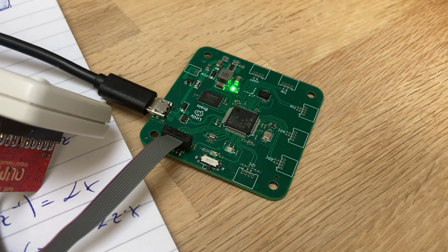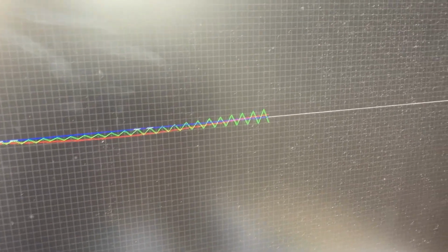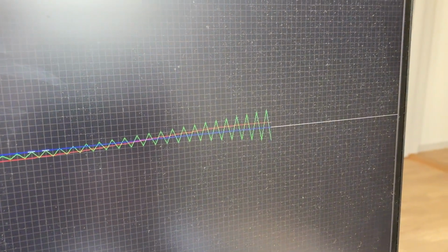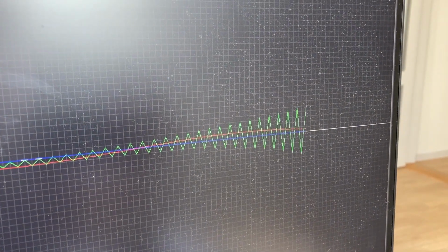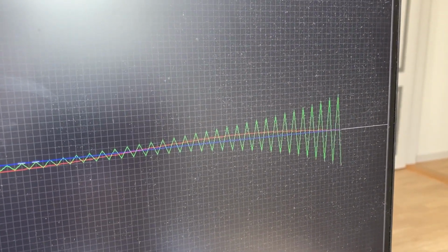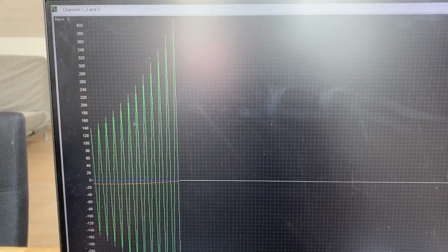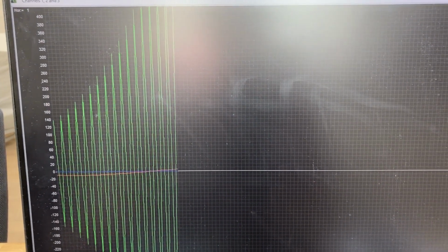So here we now have the unstable IIR filter running. And going back to the serial oscilloscope, we can see the input-output behavior. So as you can already see, the red curve is actually the input, and now the green curve is the output, and that's already oscillating, and as you can see, now it's actually growing. This is because the magnitude of beta, as we calculated, puts the pole outside the unit circle and makes this IIR filter unstable. As you can see, because I've slowed it down so much, we can really see how nicely exponentially this is growing and becoming unbounded.